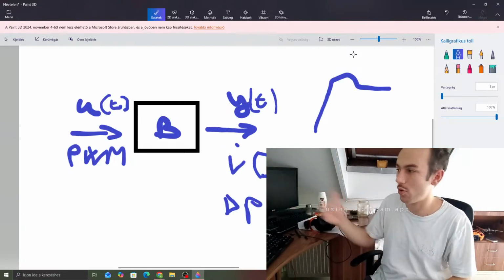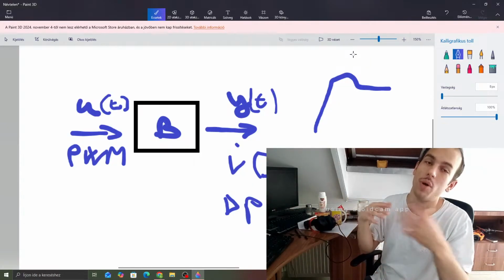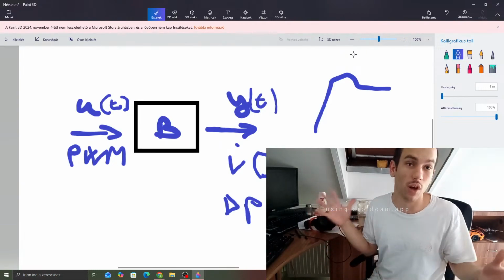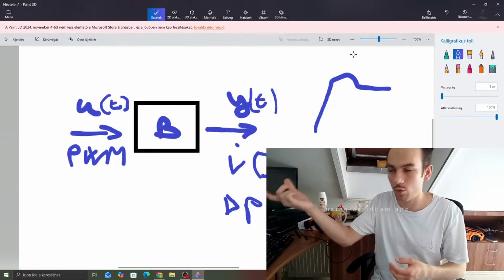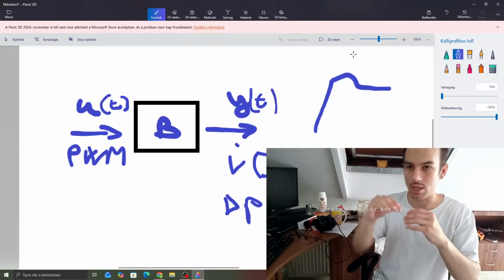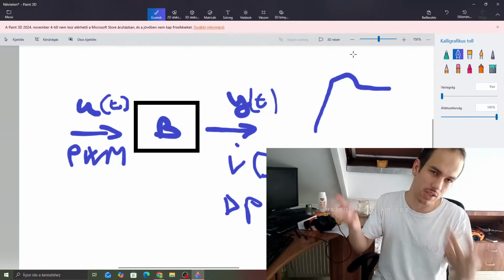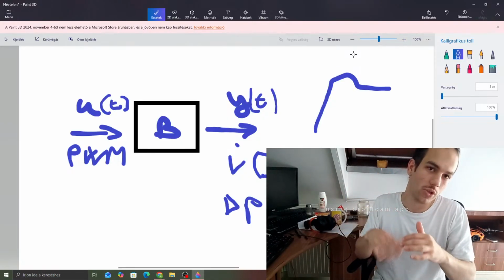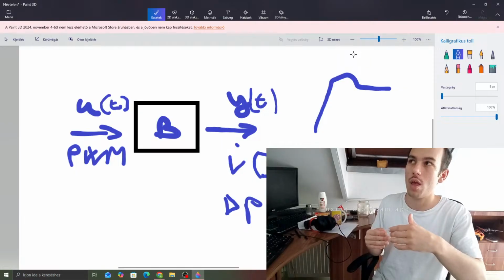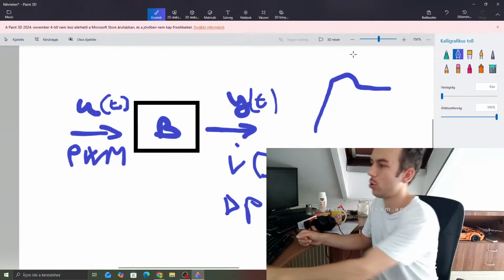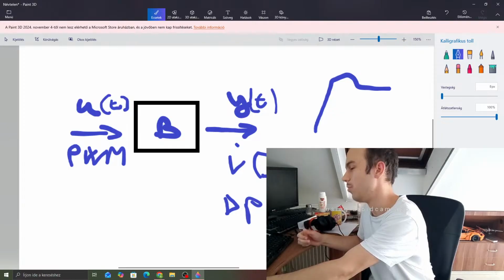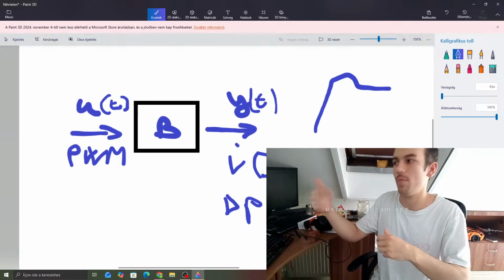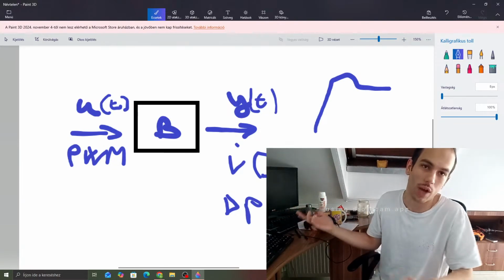If you increase the pressure, if you increase the blow air, meaning the volume of air that goes in, you can easily blow out the flame, and then it's gone. You need to know exactly how to adjust the fuel pump PWM. It's the same thing with the blower. You need to increase them proportional to each other. If you don't know how the pressure, or the volumetric flow, behaves in time, then you might have some trouble later.